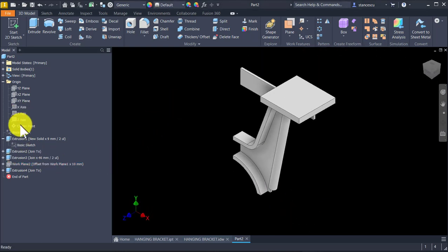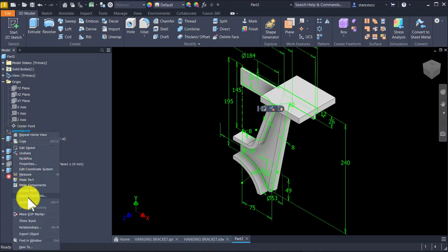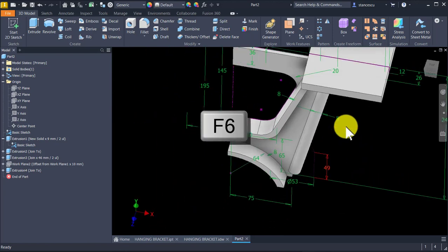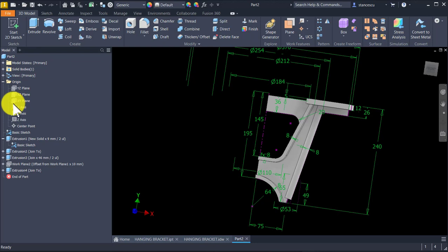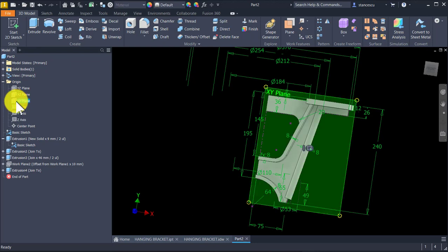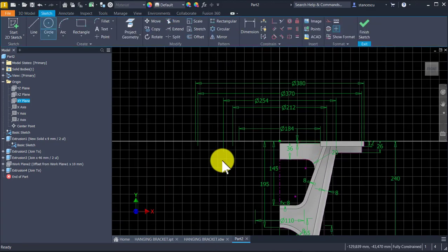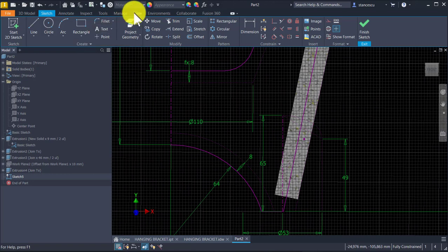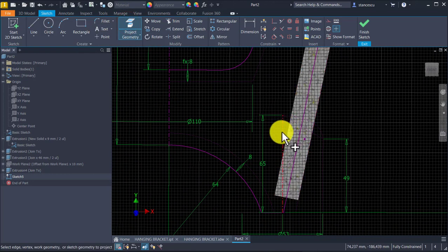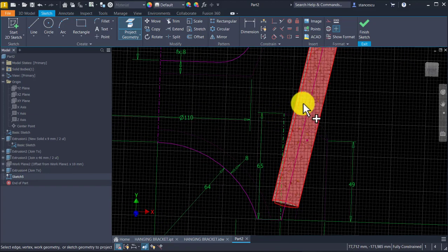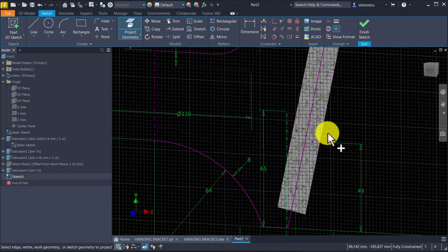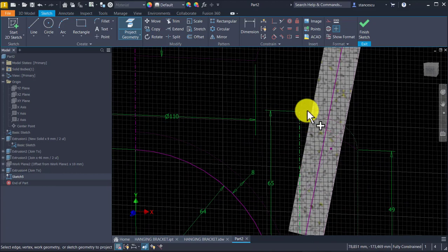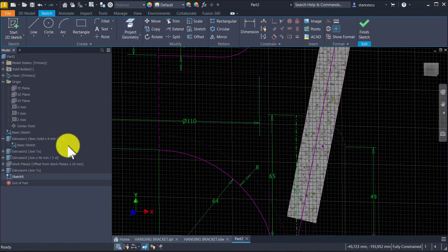Now we use again this basic sketch to create that cylindrical volume which is here. I project those lines in a new sketch in this plane XY. F7, and we project some lines. Project lines and arcs. This arc, this line, and the upper arc.